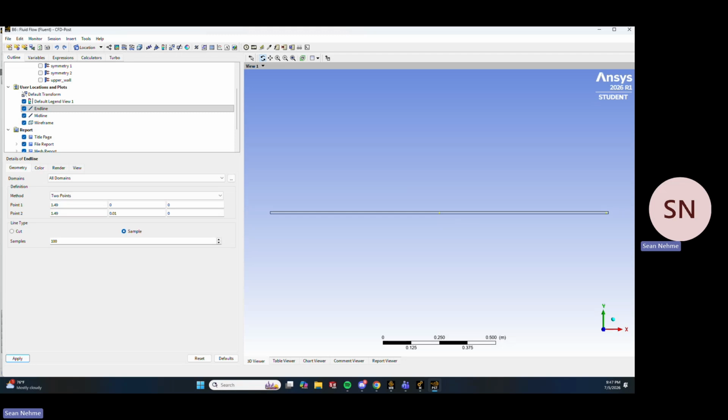And then this is optional, but the video did it, and it actually is a good visualization. We'll put our developing flow line. For developing flow, we will do some point below before the midline. So 0.15, 0.15, 0.01. Apply. That should be somewhere at the beginning here. That looks awesome. Now we have all our lines created on our sketch.